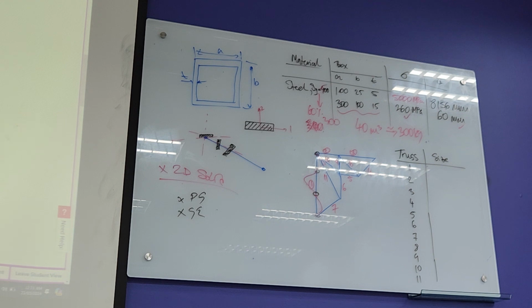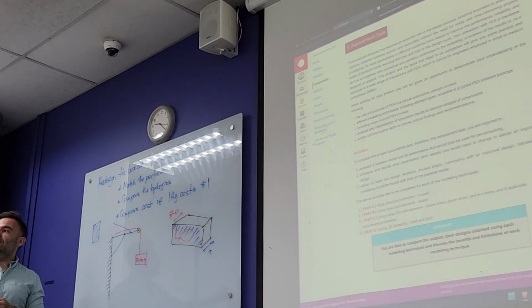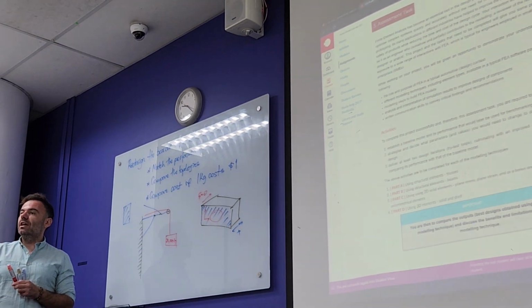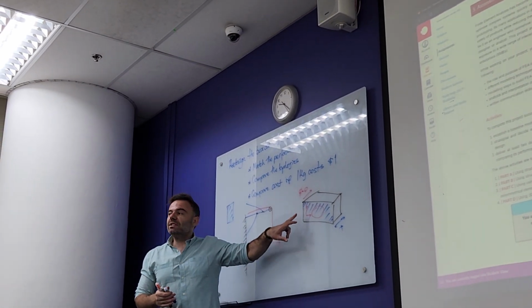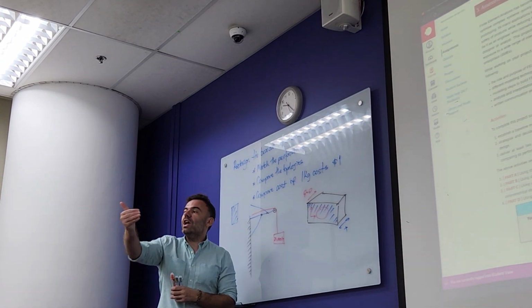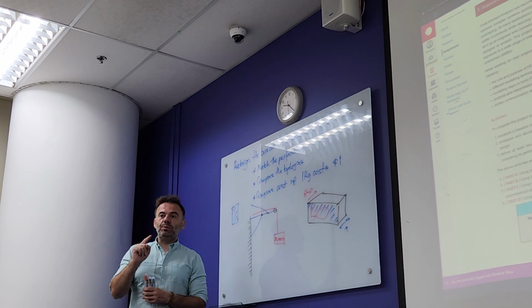Yeah? So when we say plane stress, it means all the stresses are in a single plane. And here is the zero stress. So there's nothing happening in that 3rd direction. That's what plane stress is. Plane strain is the same story. Strain happens in a plane and there's no change of thickness through that. So that's the difference between them.